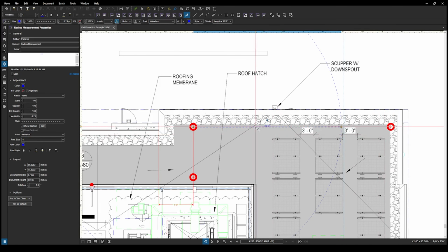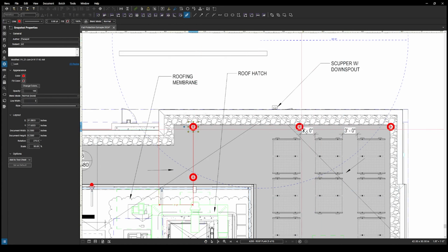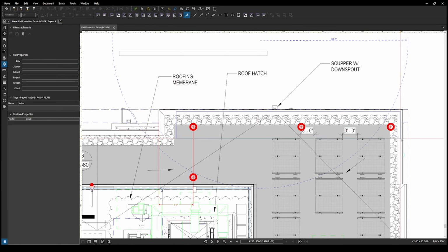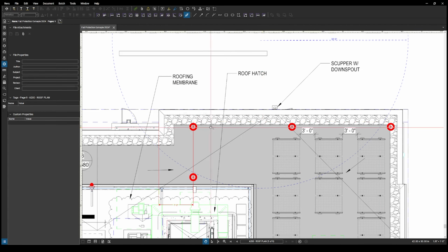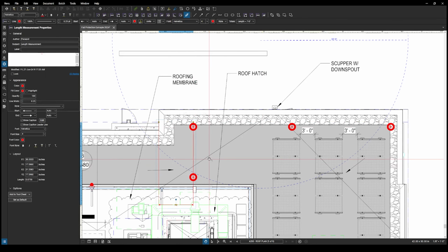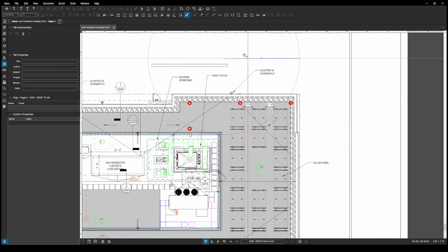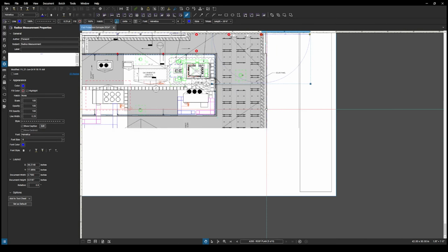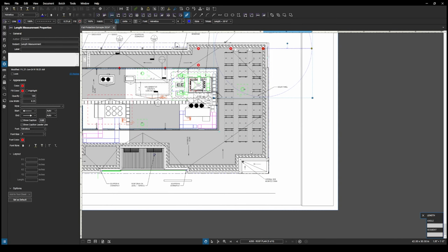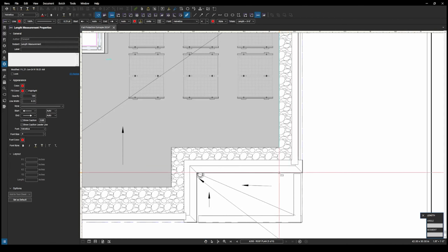Okay, so I know that my roof anchor needs to be in that location. And I actually don't need these dimensions anymore, because I can just copy and adjust anchors along the axis by using the built-in Bluebeam tools. So at this point, we're going to convert from doing wall anchors to roof anchors here. And so the cable continuously is going to go through all of these. So from here, I'll measure another 30 feet. And so, yep, that's around here.